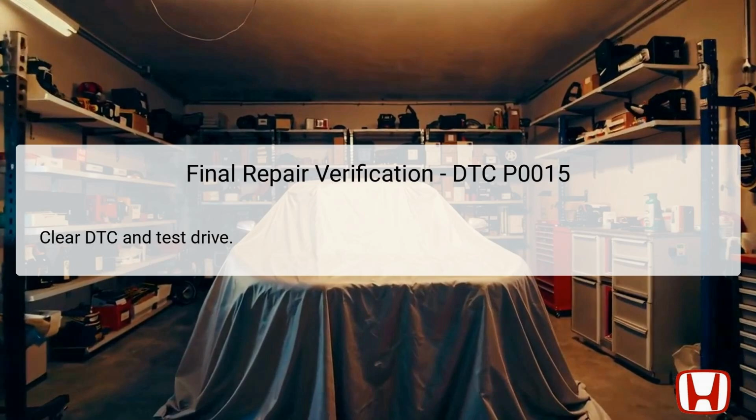Once the code is cleared, conduct a test drive under various operating conditions to fully evaluate the vehicle's performance. Pay attention to engine behavior, including responsiveness and idle quality, and remain vigilant for any returning symptoms or warning lights. If the DTC does not reappear and the engine runs smoothly, it indicates a successful repair. Document the results of the test drive for future reference and verification.